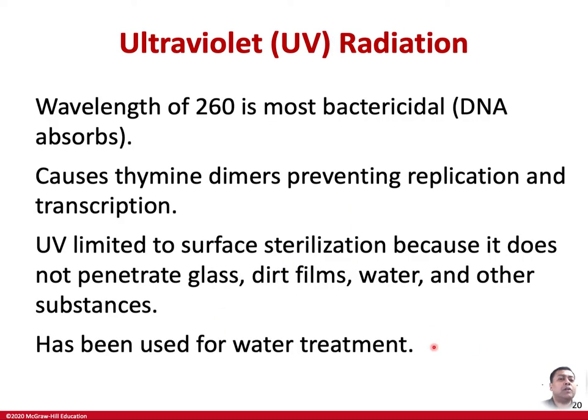It is routinely used also in operating theaters. On the other hand, it is also used for water treatment, and these can even be installed in households or small restaurants, where you have a chamber with a powerful UV light emitting a 260 nanometer wavelength. Next to the UV light, you have a clear water chamber or water pipe through which water is flowing.